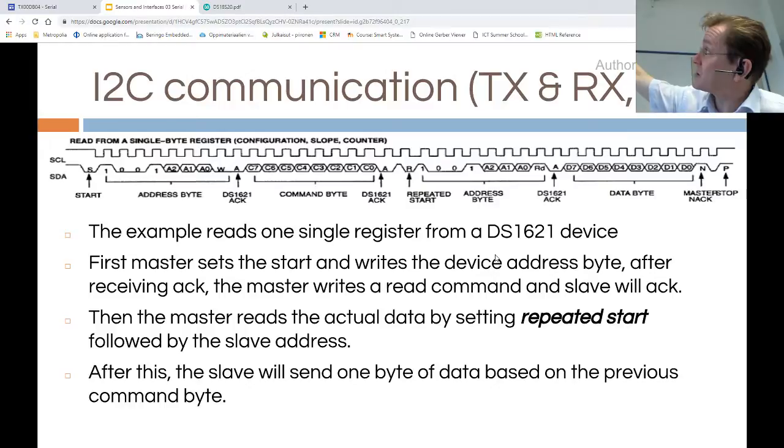The other pin should be able to both read and write. So you put a control to the pin so it's open collector, kind of, with a strong 0 and weak 1. Then you can actually release the line.